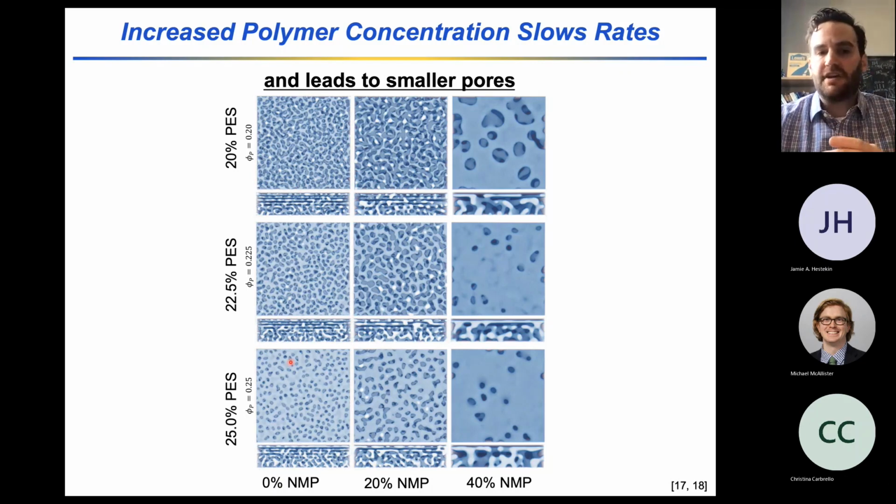So it's not as straightforward as saying that slower vitrification fronts will lead to larger polymer structures, because this slower vitrification front is a result of the polymer dynamics being slower itself, and so they can't grow as rapidly. Though as you continue to move to more solvent in the non-solvent, you do ripen the structure and end up with larger pore sizes. This speaks to an area of open opportunity in understanding the non-solvent induced phase separation technique: the non-equilibrium processing of the material.